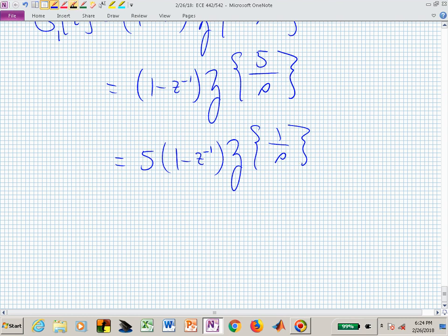And if you wanted to think through what's happening, you could now say, oh, what's going to happen now? This was the handshake and a wink. What's happening with this script z? Well, first I have to inverse Laplace transform 1 over S. Then I sample, and then I z transform that sampled waveform. What happens when I inverse Laplace transform 1 over S? That's just a constant, isn't it? 1. Now I said let's sample that.